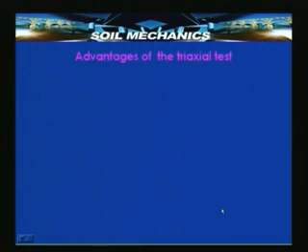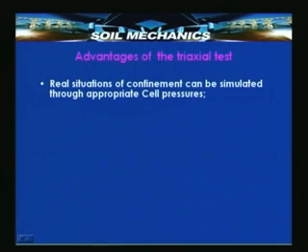Now, why do we need to conduct this triaxial test? Why do we need to understand the importance of this triaxial test? It is because there are several advantages associated with the triaxial test compared to the direct shear test. The advantages are: 1, real situations of confinement in the field can be simulated. As I mentioned just a few slides ago, a soil is under a certain confining stress at a given depth in nature, in the field.